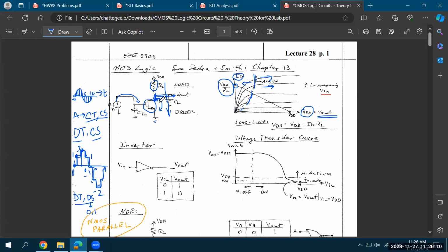So the VDS, the drain to source voltage drop of the transistor, is almost zero. You're effectively around this point, where the x-axis value is almost zero. Let's just consider this small region over here. The drain to source drop is almost zero, which means that the current through the system is determined by VDD over RL. So that's this point.